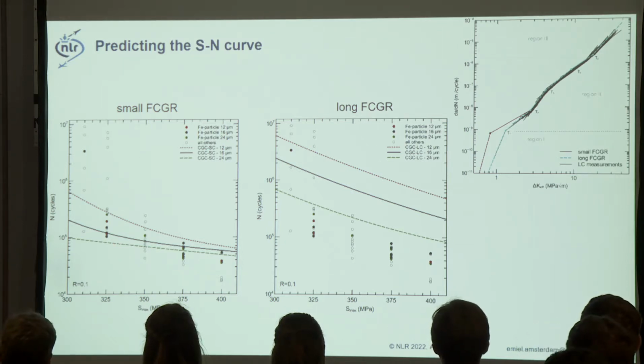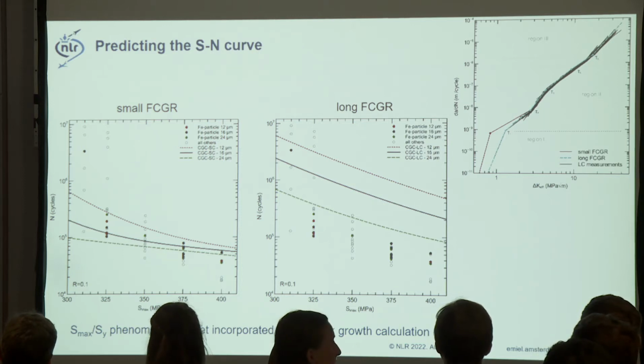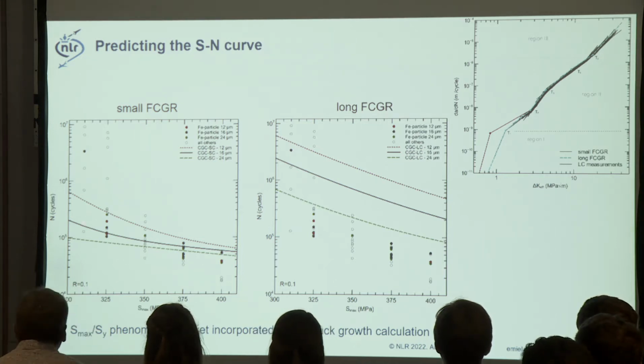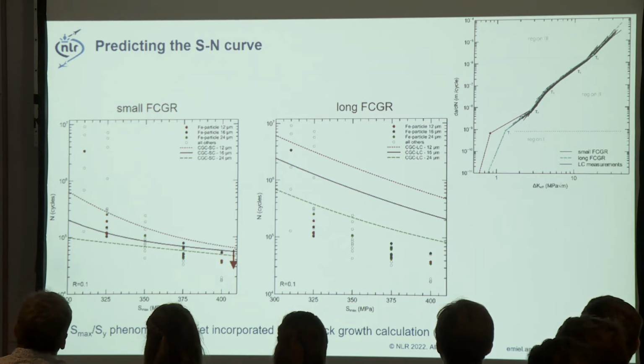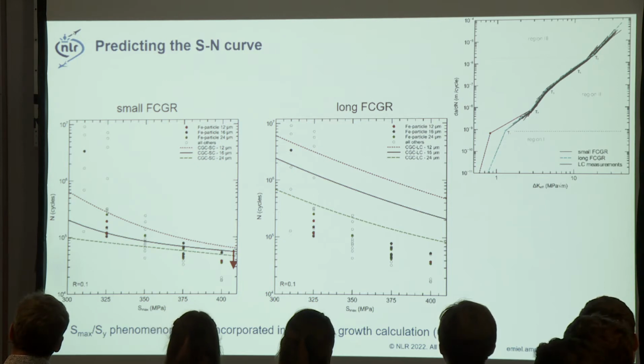If we use the long crack growth rate, then we get unconservative results. However, we did not incorporate the maximum stress phenomenon yet, and we measured the crack growth rate at about 300 megapascal. So we are quite good here, but we think that we still need to incorporate the effect to also get more accurate results in the regime near 400 megapascal.